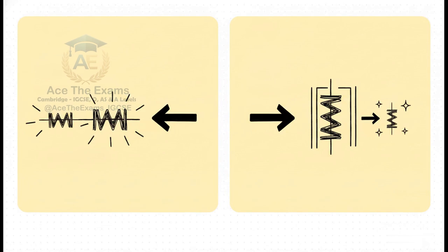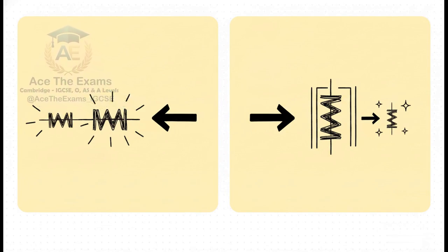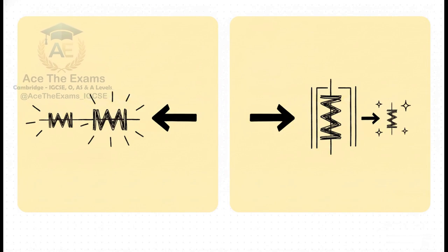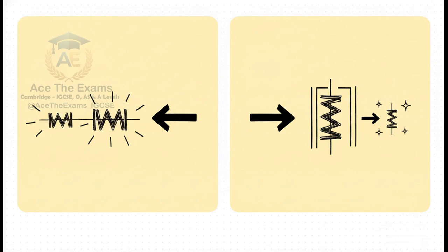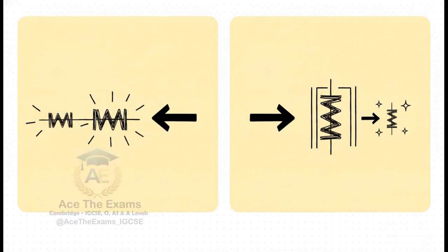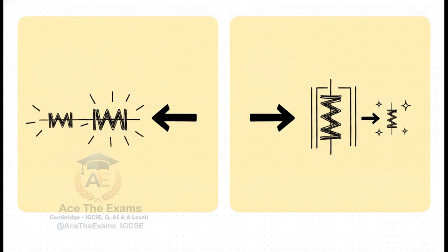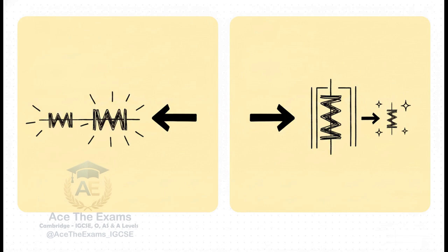So how does this translate into our math shortcuts? Well, for series circuits, since the voltage just adds up along the path, the total resistance is simply R1 plus R2 plus R3. You just add them right up. Super simple. Parallel circuits are the inverse. Because voltage is constant across all those branches, we divide it out, which leaves us with this formula. 1 over total R equals 1 over R1 plus 1 over R2 plus 1 over R3. Those two little formulas, they are absolutely your master keys for unlocking and simplifying even the messiest circuit diagrams.